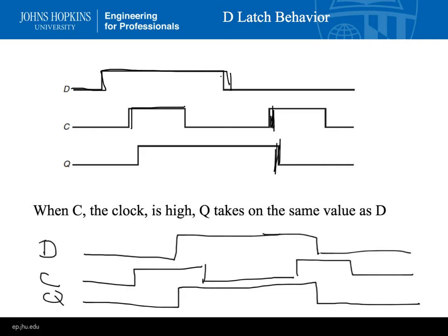So I added another example to understand latch, where the output goes with the input as long as the clock's asserted while it happens, to distinguish this from flip-flop. Here the signal goes up, the clock is asserted, so Q goes up with it. And here the signal goes down, the clock is asserted at that time, so the signal goes down with it.